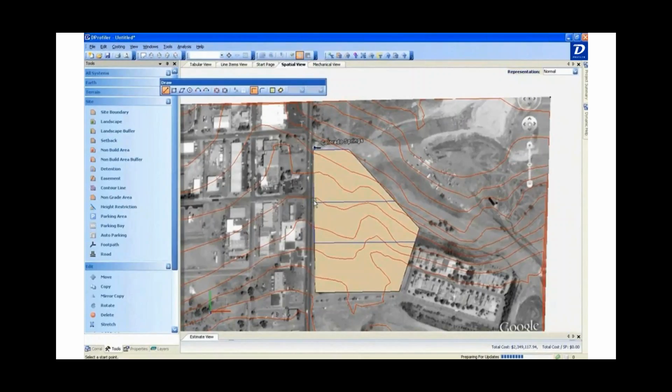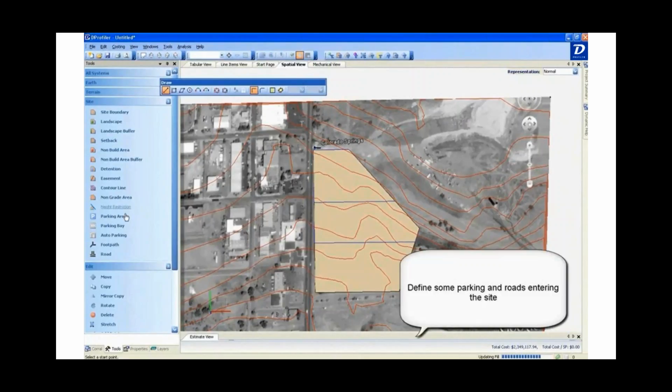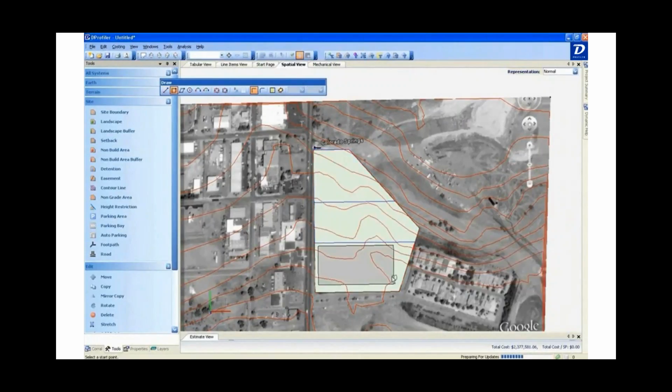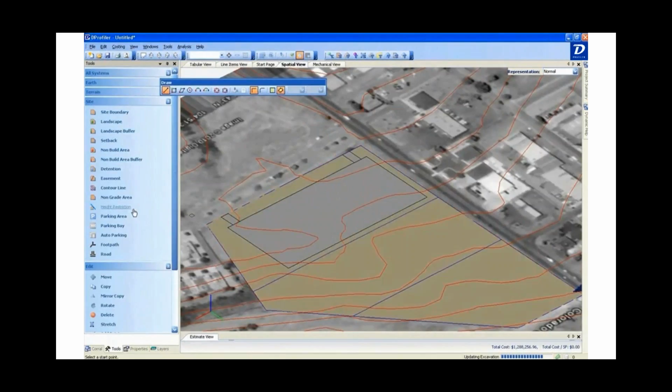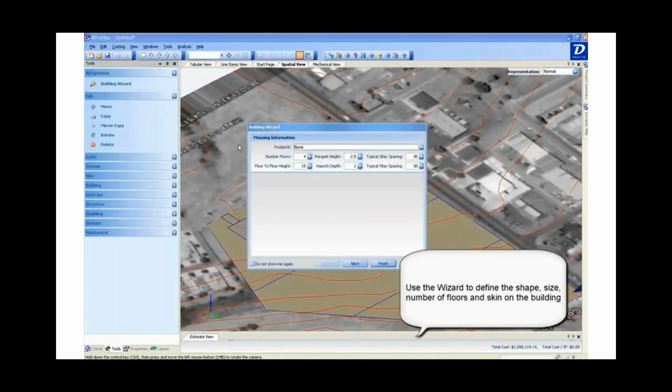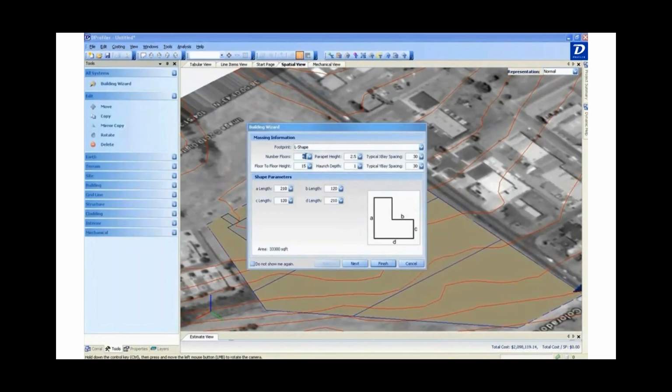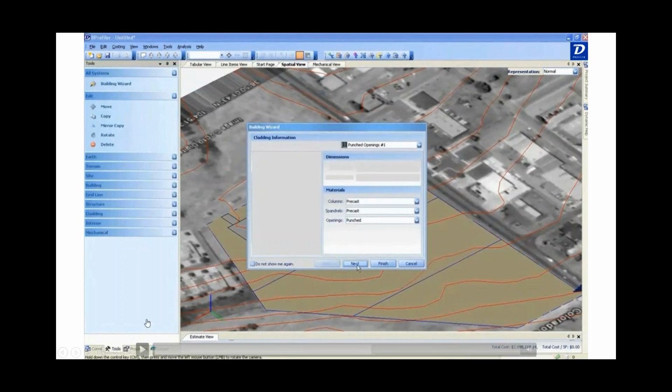As we start to introduce more elements into the project, the same things are going to happen. We introduce parking. The profiler goes into the database. It looks for your recipe of costs to apply, and it uses the quantities of what you've drawn for quantifying those line items.